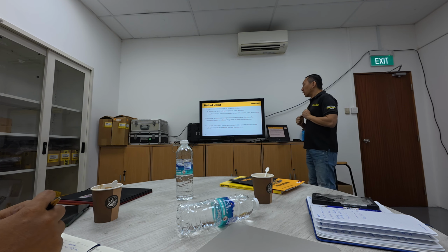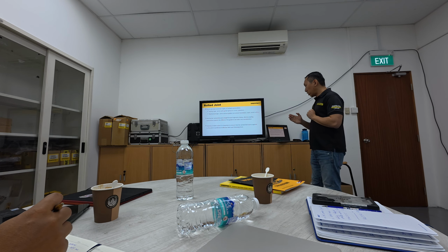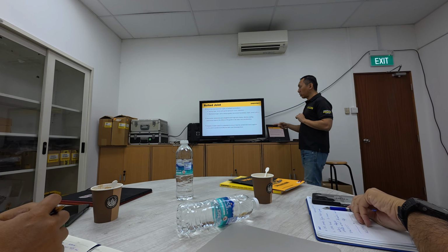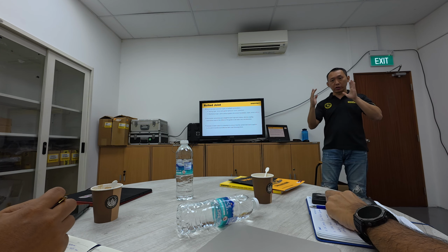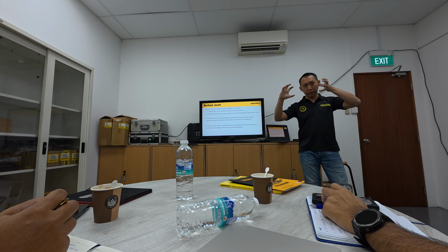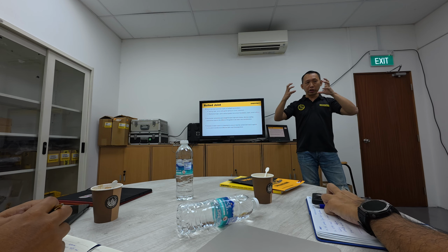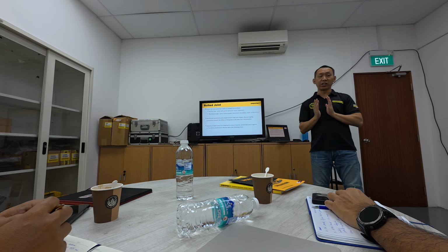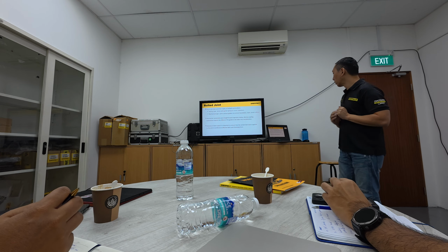However, in all cases, whether it's the sealing or mechanical type, it's important to ensure that the correct load is applied to the joint to produce an effective clamping force. That means you need to ensure the load on the joint is correct. Too loose, not enough, you leak. Too tight, you might damage the gasket or you will damage the flange. So you must ensure the correct bolt load is applied.